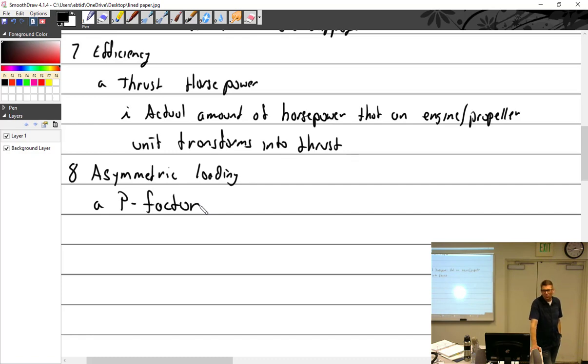So anyway, this guy, he's an RAF pilot. He flew in the war, thousands and thousands of hours. Should I back up the story? When you take off in a tail-wheeled airplane, you have gyroscopic precession. You have this big disc, right? And gyroscopic precession says that whenever you put in an input, it's going to happen 90 degrees later. Their engines are spinning to the left. You have to think of this big disc of the prop.